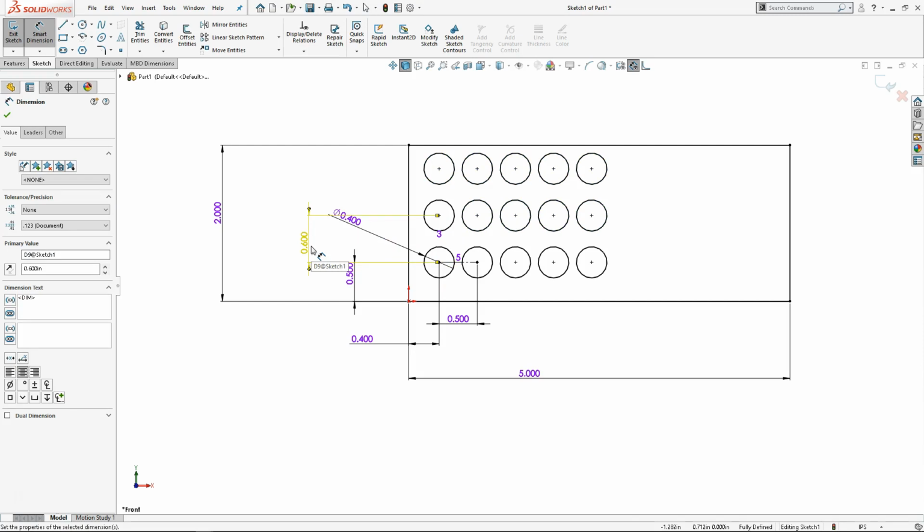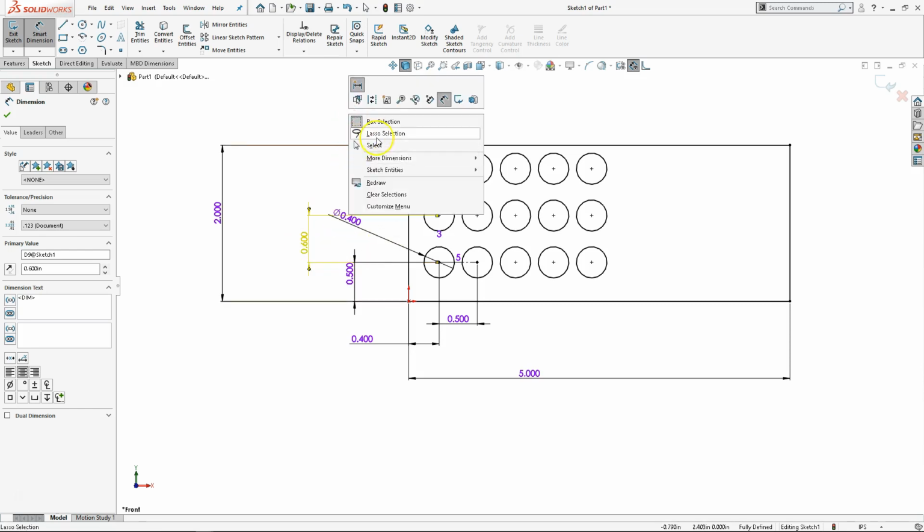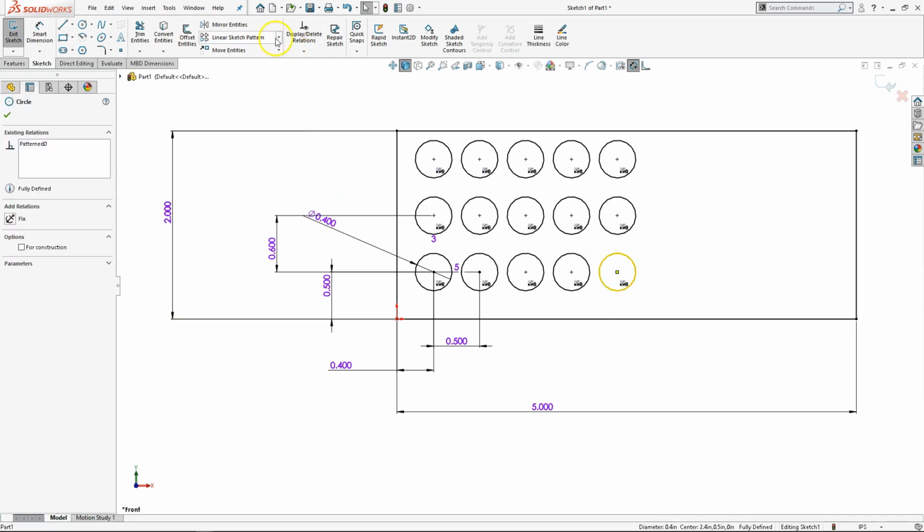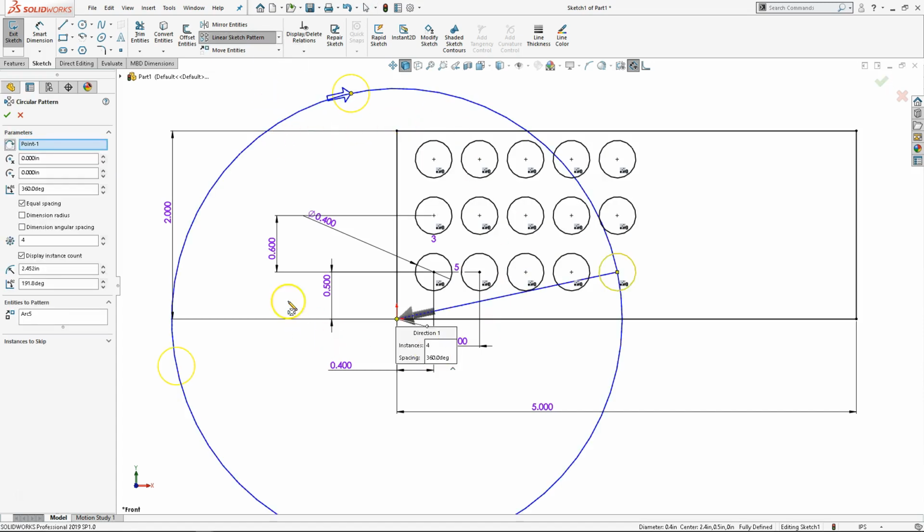Same with the circular sketch pattern, is that it's going to ask for one more piece of information. So I'm just going to try and do that on top. We'll pick one of these out here, and your circular sketch pattern is going to be underneath. Shows you the circle, and then we can either dimension the radius. We have a total of 4. Let's make that 8. And one of the things is it's always going to point to the origin. So if you need something different, then you can offset the X and Y position of the center and get to a new location.